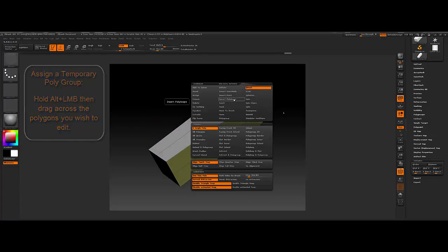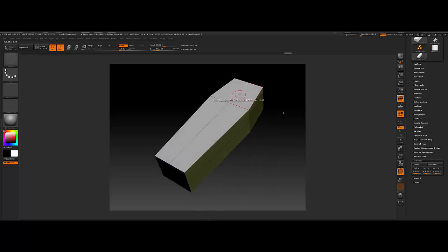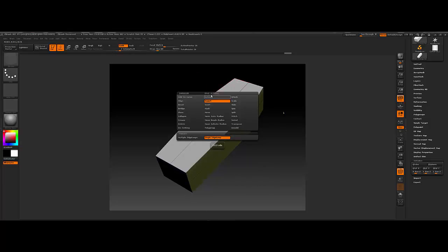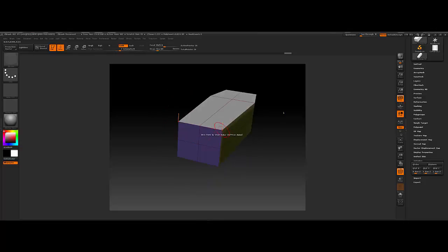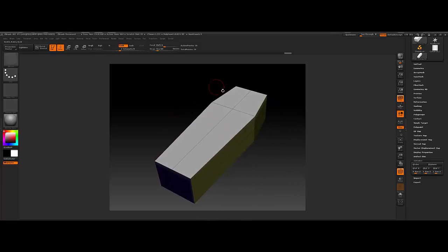We'll right click in order to bring up our kind of menu here. As you can see, we've got polygon, actions, target, and modifiers. This is context sensitive, so if we right click on this face here, we get the polygon actions. If we right click on the edge, we get edge actions. If we right click on that point, we get point actions, or the respective menu.